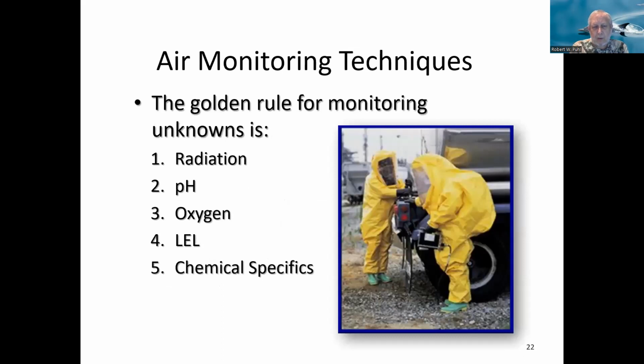Golden rule for monitoring unknowns is radiation first, and then pH, oxygen, LEL, and chemical specifics.